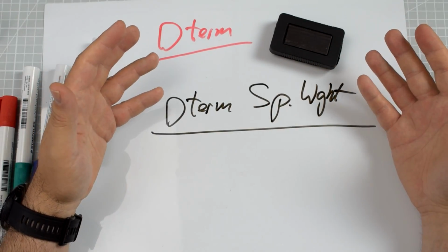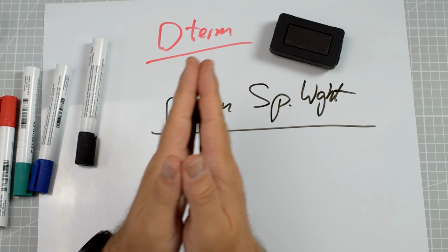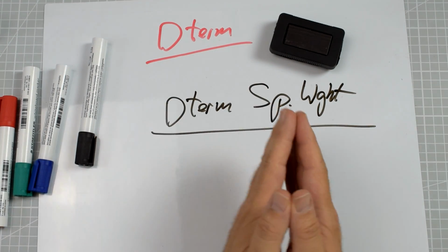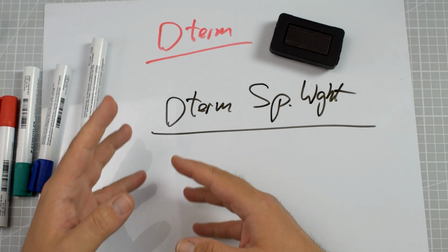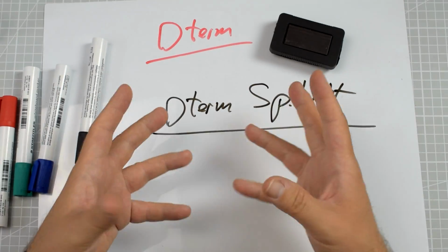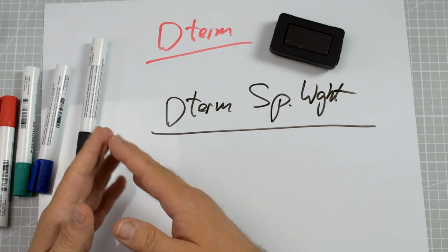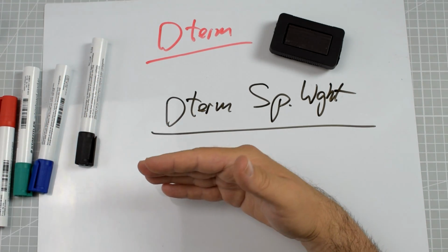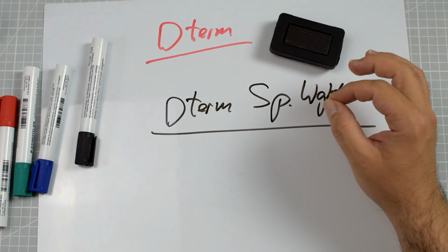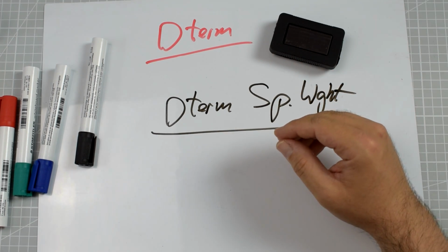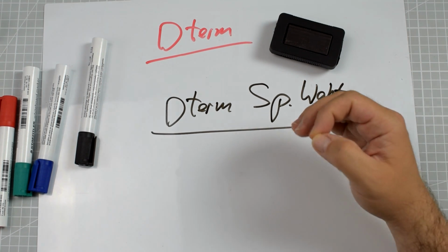It was just a multiplier in a simple equation: when the D-term setpoint weight was at 1, the D-term was computed from the error, and if you were lowering it towards 0, the input of your setpoint of movement of the stick on the axis was lowered, to be D-term computed only from the measurement at 0. On the other hand, if you increase it above 1, then the value of the error was increased, and it was more about computing the D-term from the setpoint than from the measurement.